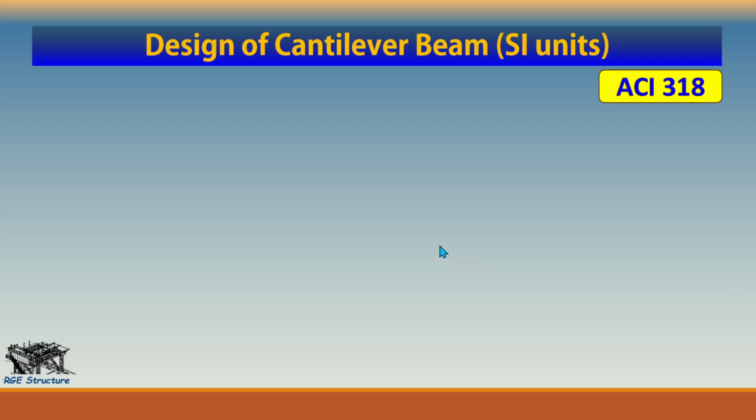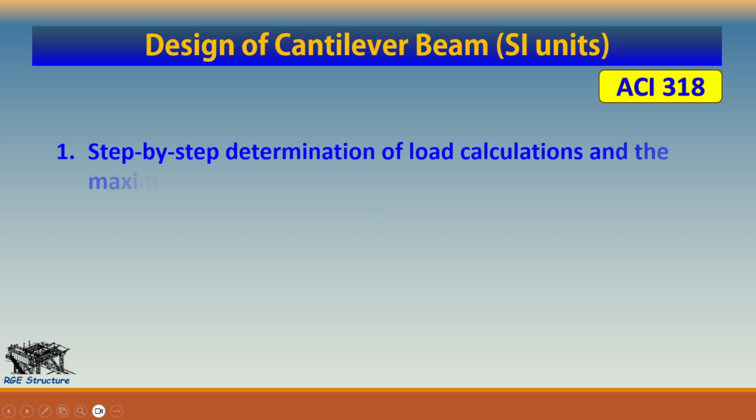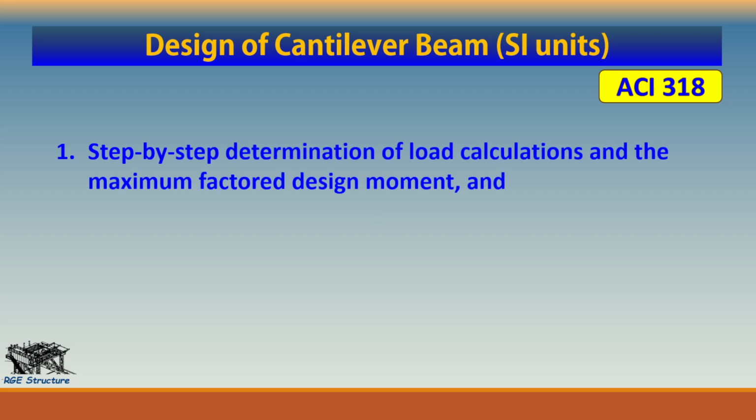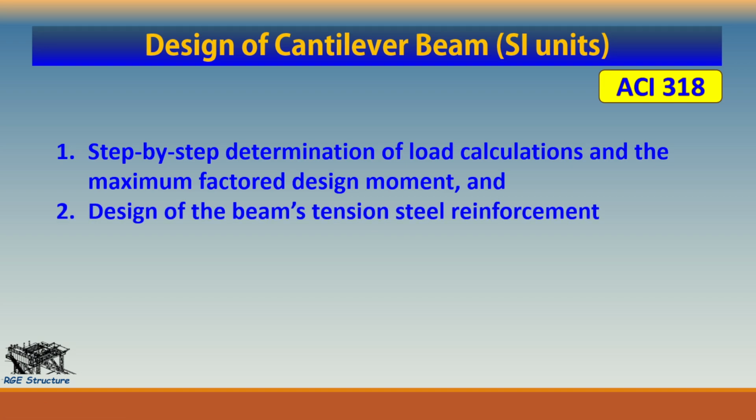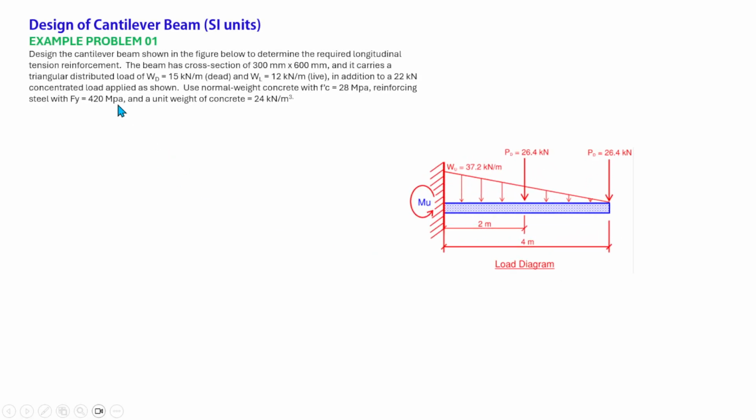Hello everyone. In this video, you will learn how to design the cantilever beam, and we'll also cover the following key points: step by step determination of load calculation and the maximum factored design moment of the cantilever beam. And the second one is to design the beam tension steel reinforcement. So let's dive into our problem.